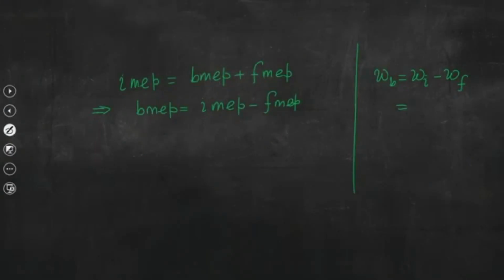So, we can write one factor multiplied by Wi, and that factor is known as mechanical efficiency. So, this mechanical efficiency eta m is Wb by Wi, and it is always less than 1. So, this is what we have discussed in the last class.